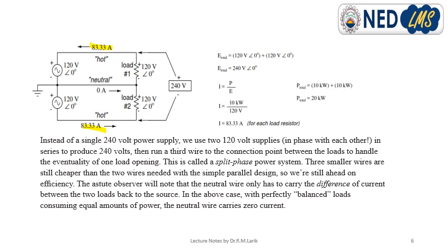That is why tourists from America visiting Europe must carry small step-down transformers for their portable appliances, to step the 240 volts AC down to a more suitable 120 volts AC. The US standard is 110 or 120 volts at 60 hertz, and the European standard is 240 or 220 volts at 50 hertz supply. It is from the point of view of danger, risk and safety.